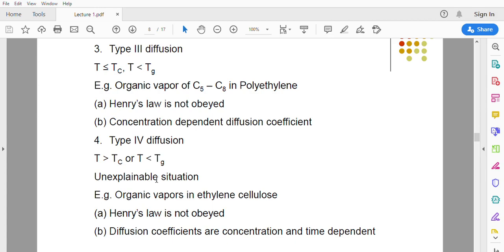Both are present in the supercritical condition, and you want to separate them using a polyethylene cellulose membrane. Polyethylene cellulose at environment temperature is stiff. So the glass transition temperature of this polymer is higher than the atmospheric temperature.